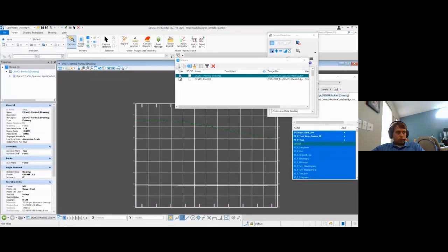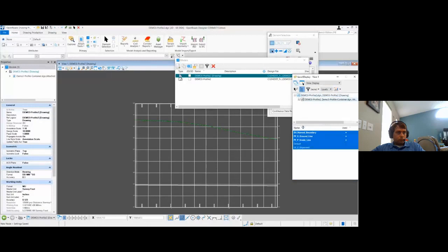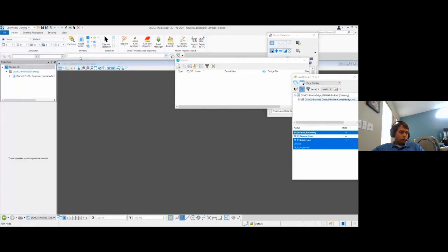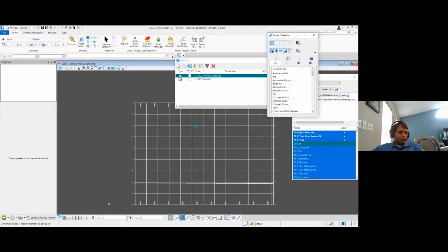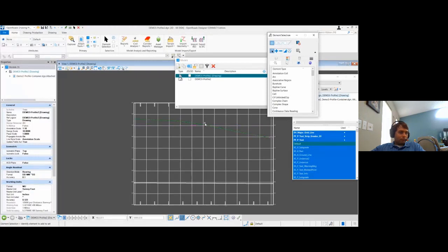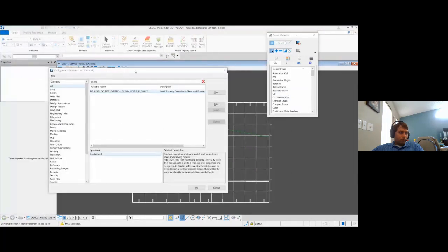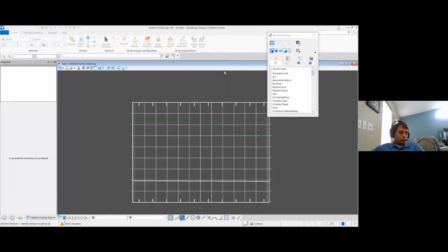So if I try to turn something off here, like ground line, save settings, and reload the file, the display overrides is going to bring it back, right? So it should be back on. I'll pause the video, turn the variable off, and do that again to show that the variable isn't controlling that either. So you see I reloaded and the variable's off.